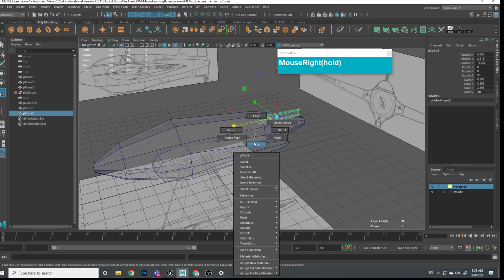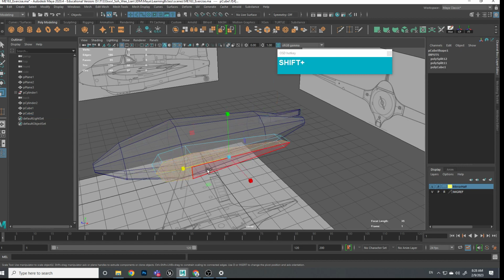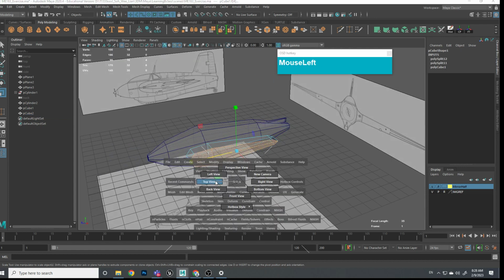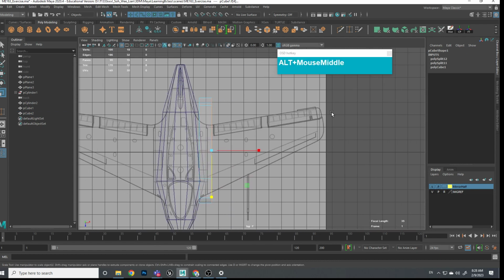From now onwards, we can just select these faces, and we can do a quick extrude, or we extrude it out until it reaches the wingtip. In fact, if you do not want to extrude, you can just simply move the faces until it reaches the wingtip like that. Then you can use scale. You can scale it uniformly first, because we know that it's tapering from the front view as well. Then press W and have it match the swept back.